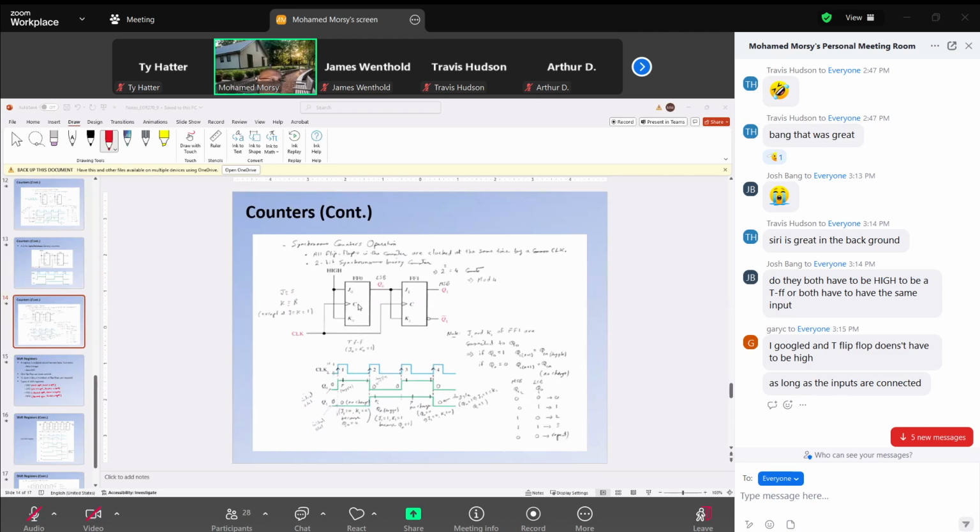Now, based on this, let us go ahead. For the clock pulse, both flip-flops are positive edge triggered, and the change is related to CLK, so we put arrows as the positive edges. The initial status of Q0 and Q1 are zeros, but this can be different.